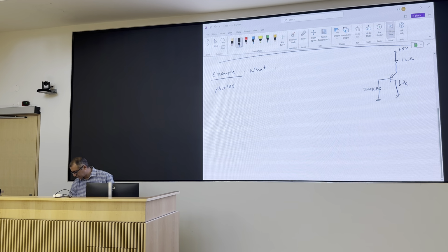So at the top, I have an N region, in between I have a P region, and at the bottom I have another N region. But because of the way these devices are made, I don't have two exactly similar diodes at the top and bottom. The diode between base and collector is a little bit different than the diode I have between base and emitter, right? So this is base, collector, emitter.